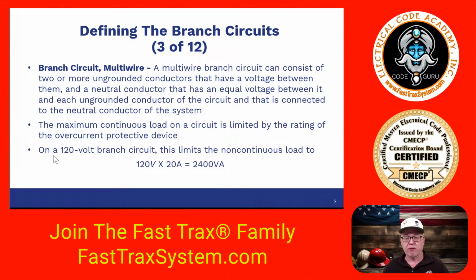Okay, so for example, if I have a 120 volt branch circuit, this limits the non-continuous load to 120 volts times 20 amps, which is 2400 VA or 2400 watts. So that is the maximum that we could have on that circuit if it's non-continuous.